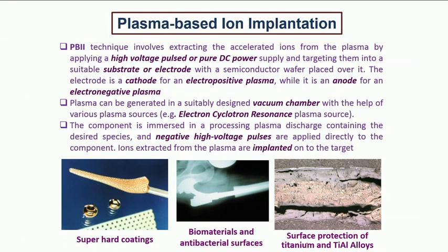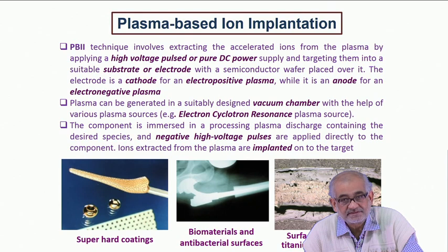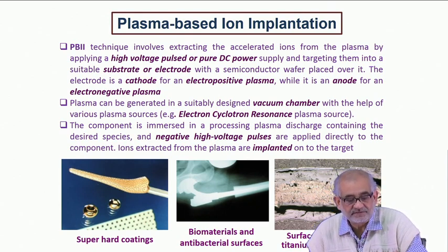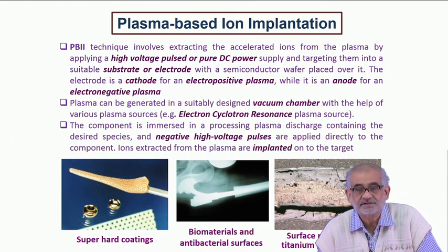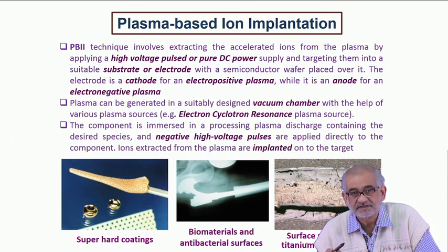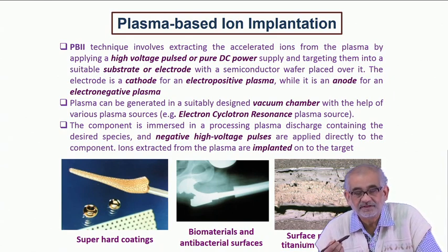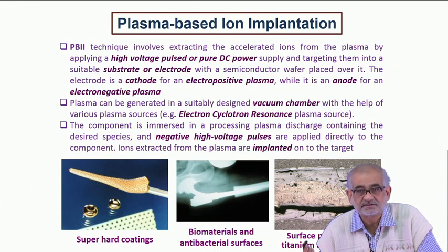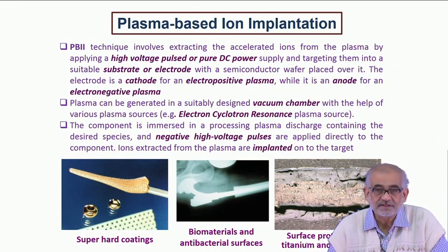The other processes, I already mentioned, plasma nitriding is exactly the same as gas nitriding or even liquid nitriding. That means you create a nitride layer onto the surface, and like we discussed in the previous lecture in detail, the first layer could be the zeta nitride, and then we can have epsilon nitride or gamma prime nitride and so on. So anything from Fe4N to Fe2N, a mixture of that graded from the surface to the core, and that's the reason why we get all this high hardness, high wear resistance, even fatigue resistance, corrosion resistance, and so on and so forth. So exactly the same.